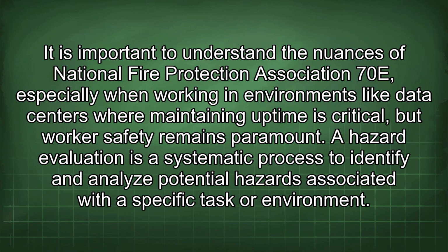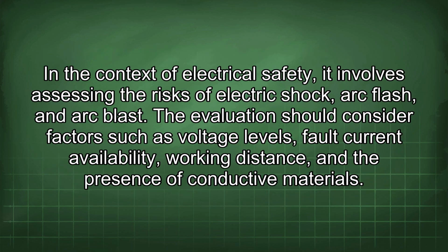A hazard evaluation is a systematic process to identify and analyze potential hazards associated with a specific task or environment. In the context of electrical safety, it involves assessing the risks of electric shock, arc flash, and arc blast. The evaluation should consider factors such as voltage levels, fault current availability, working distance, and the presence of conductive materials.